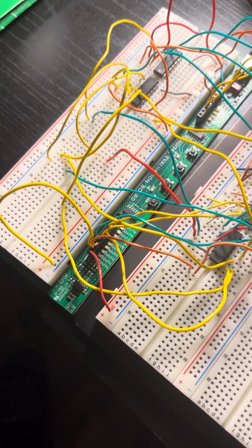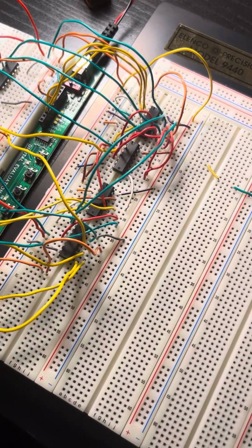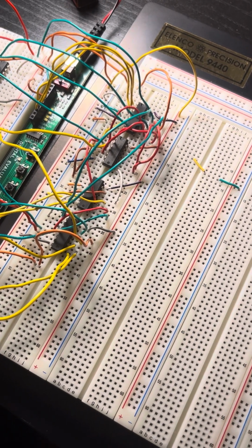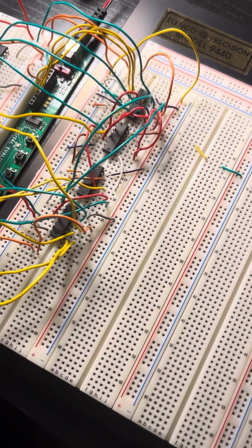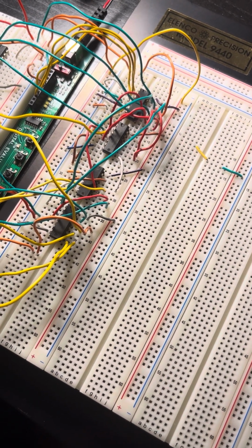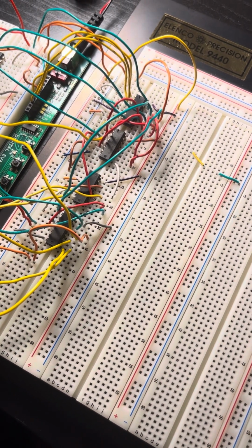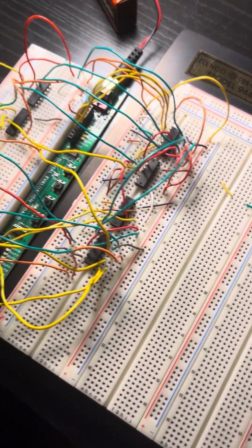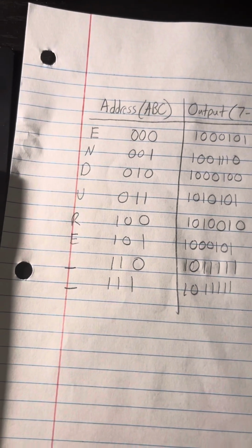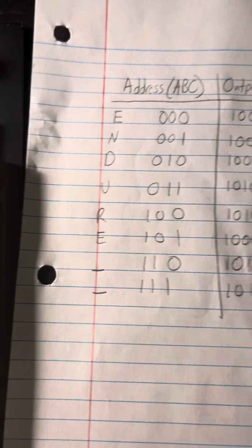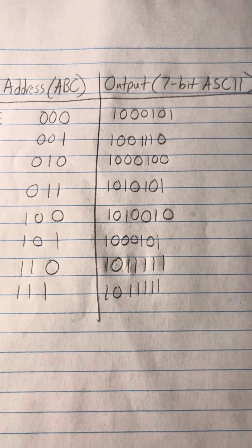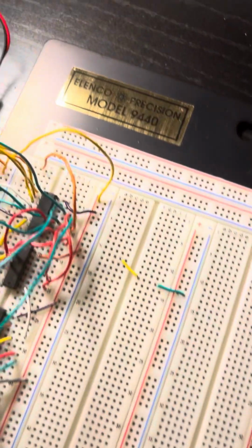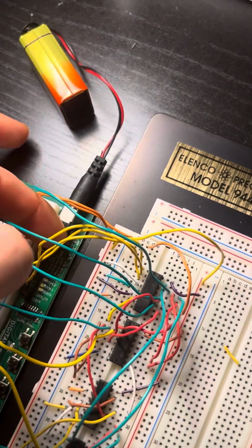While ideally this circuit could be easily realized by simply using multiple input NAND gates to connect decoder outputs to the ASCII bits, my hardware limitations forced me to be creative in using De Morgan's theorem and frequent inversion to make logically equivalent circuits. Nonetheless, here's my demonstration beginning with input address 000 corresponding to letter capital E with a 7-bit ASCII output of 1000101.